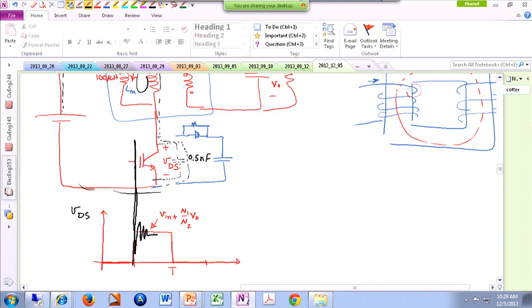So before, you were designing the system and say, oh, for instance, this is only, I don't know, 100 volts. So if I buy a 200 volt switch, I'm going to be fine. But then you realize that the first time you build a system, your switch is dead, because your switch was only capable of handling 200 volts, but then this was like 1,000 volts. It is a very short period of time, but just a little bit of extra voltage may actually harm your switch. So you can see that your switches keep getting killed, and that's actually the reason.